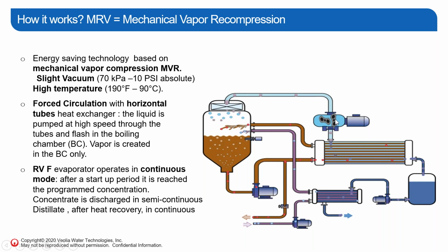This vapor is basically then turned into a hot steam. This goes through a heat exchanger. As it's going through the heat exchanger, it condenses, so it transforms into a liquid, goes into this condensate holding. So this condensate here is still at around 80 degrees Celsius. So there's a lot of heat here, and you really don't want to necessarily discharge 80 degrees Celsius water. So we then run this condensate through another heat exchanger where it goes from about 80 degrees Celsius down to 40 degrees Celsius with its interaction in the raw wastewater. Your concentrate line, basically what's inside of your concentrate here goes through this heat exchanger with the vapor.